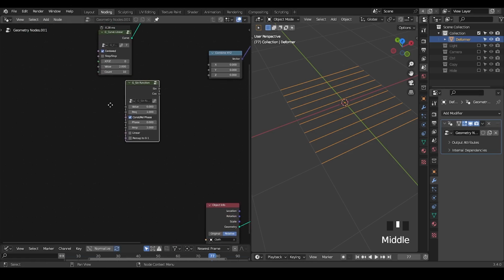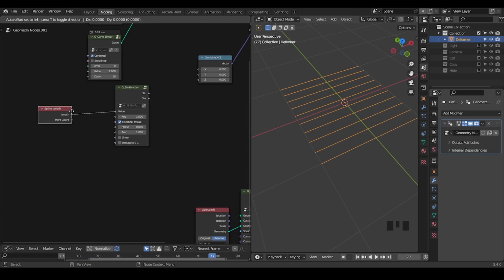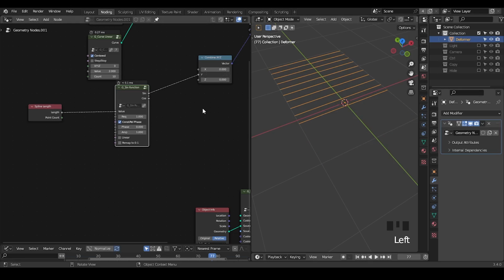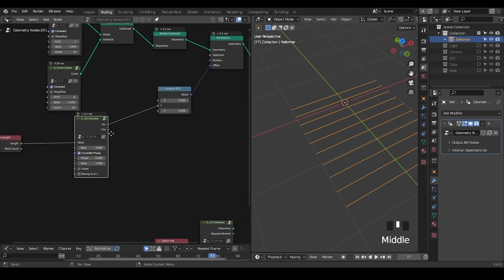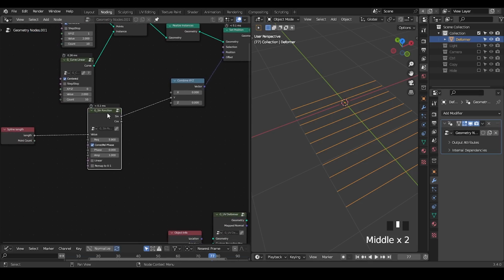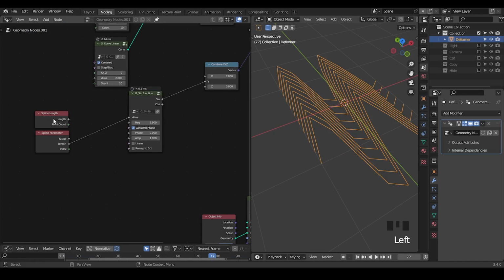Okay. So we're going to use the spline length in order to drive the value. So let's take a Y. Let's increase the frequency. You can see it does not really work very well. The spline length is actually a single value, so let's actually take a spline parameter. Yes, now it started to work. So every point has a different length. So maybe this point is 1 meter, that point is 2 meters.